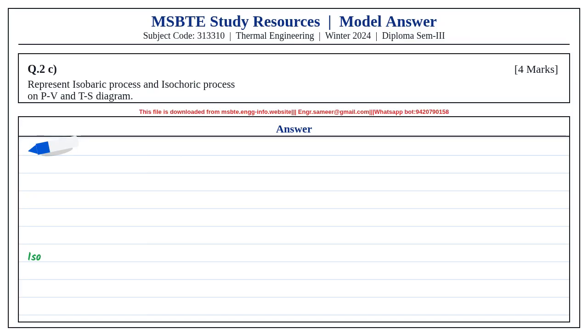Question 3c. Explain construction and working of forced draught cooling tower with neat sketch. Forced draught cooling tower consists of a fan, spray nozzles, circulating pipe, water tank, eliminators and pump. Hot water is sprayed from top.